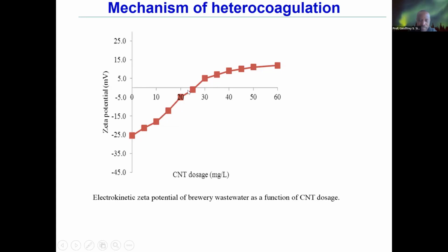What that means is the solution was becoming more positive, losing its negativity, meaning there was some sort of neutralization of the colloidal materials by the carbon nanomaterials. So in conclusion, the mechanism that is used by carbon nanotubes in this case is basically adsorption and neutralization.